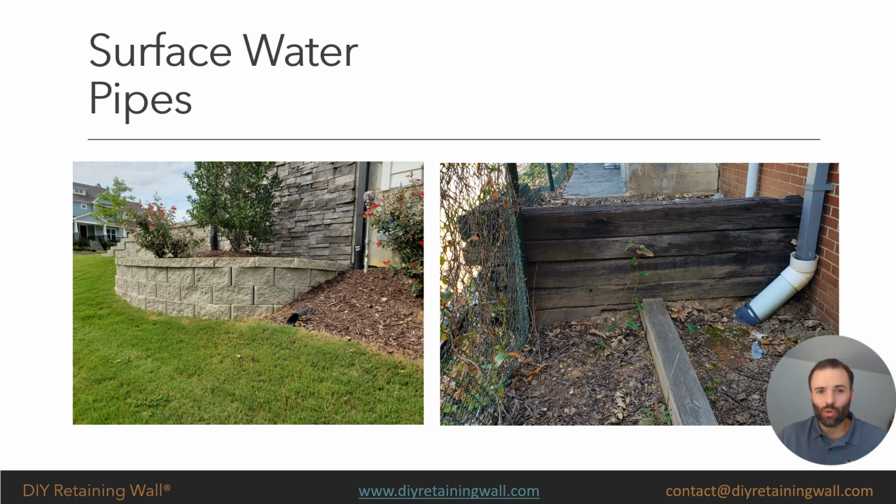Next, we want to control man-made water sources behind the wall. The most common thing to consider is the gutter downspout from your roof. If you have a gutter behind the wall, it should be piped to the front of the wall to avoid water building up behind the wall. The pipe should be solid, not perforated, to ensure no water escapes behind the wall.